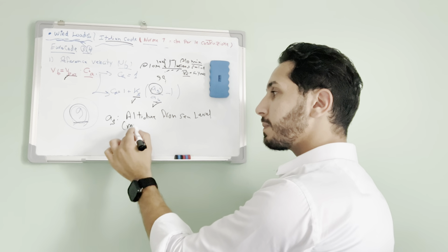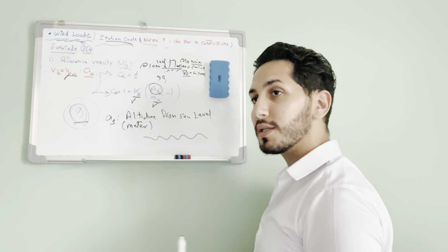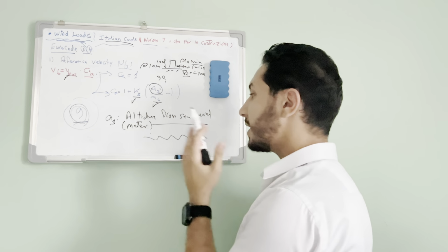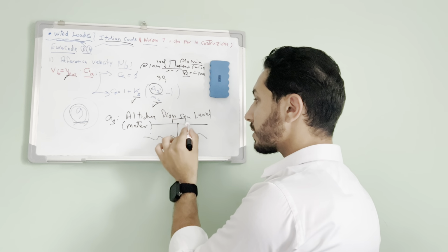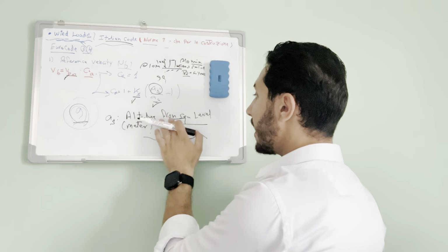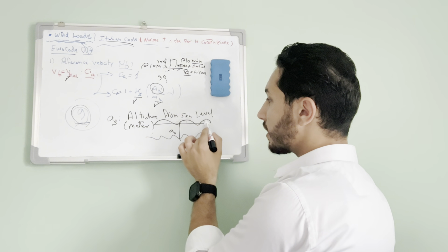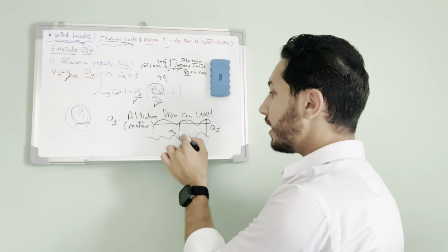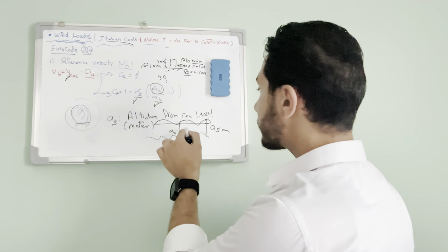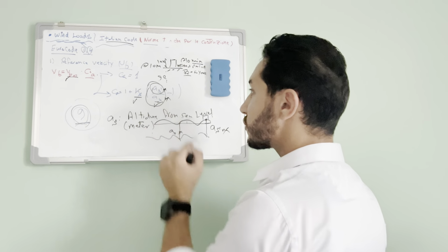And it's given by meter. So what is this? Just to understand, if this is the water or the sea level, and this is the level of the city or of your building, this value in here is called A naught. And if the ground, of course, looks like this, and you are in here with your construction, this is called AS. A naught is in meter, AS is in meter, so both of them remove one another in this equation. So this is by meter, this is by meter, so it became unitless. And now you can calculate the CA.